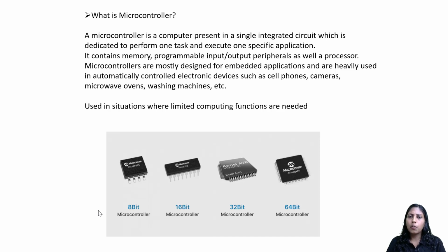In basic microcontrollers, I can tell you the program memory size will be lesser. For example, if I'm writing the AC remote code, that code can't be so much, right? The number of lines of code will be lesser, the code size is lesser. So the microcontroller I choose, for example, can be an 8051 controller. It's a simple 8-bit controller. That will be enough to store these 100 lines of code. But on the other hand, if I have a complex program, then accordingly I have to choose the controller. But anyway, I hope all are clear.